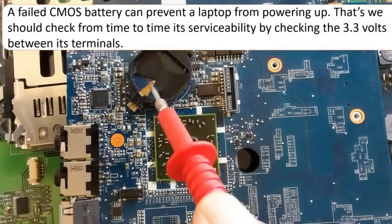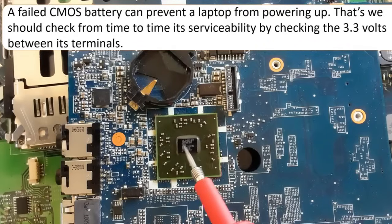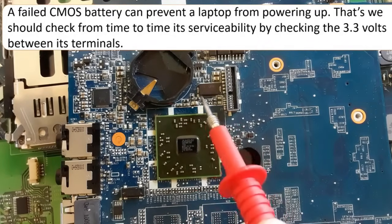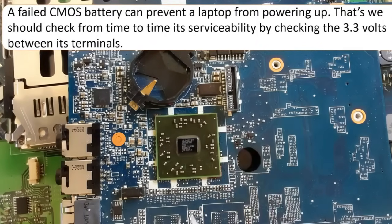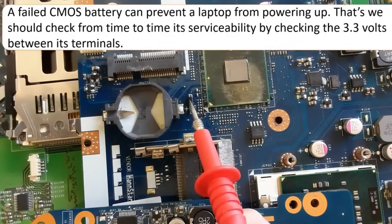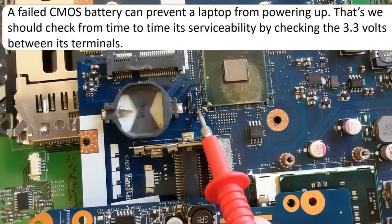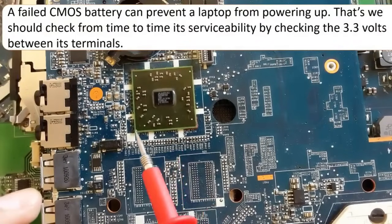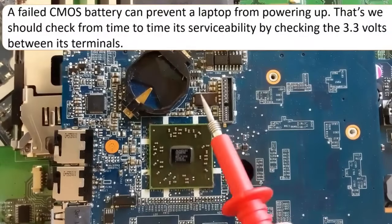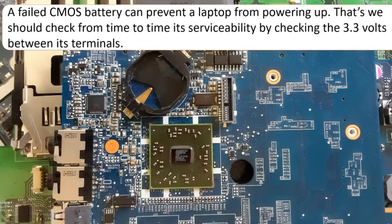We have here the CMOS battery slot. As you can see here, this is the negative terminal, and here we have the positive terminal, and here we have the ICH, and this is the crystal oscillator. Of course, you will find a crystal near to the ICH and near to the CMOS battery. Here we have the X1 or Y1. The reference for crystals is X or Y. In some motherboards you will find X and in others Y.